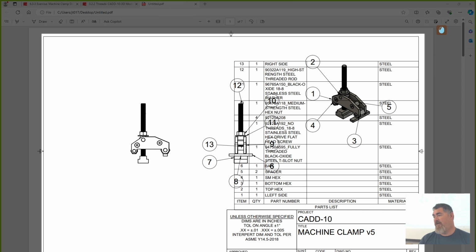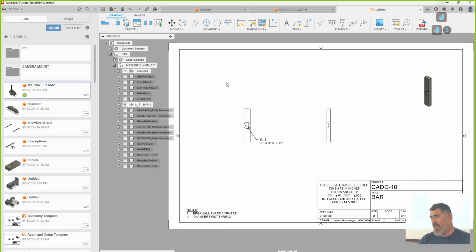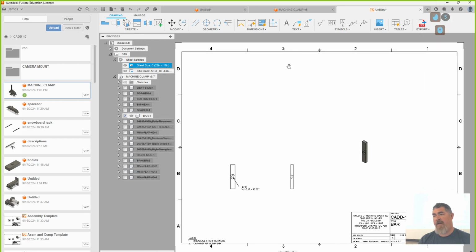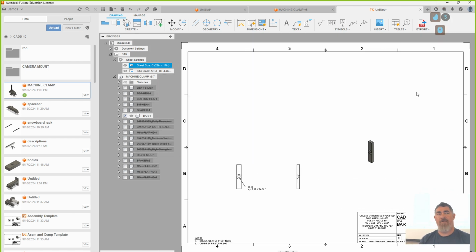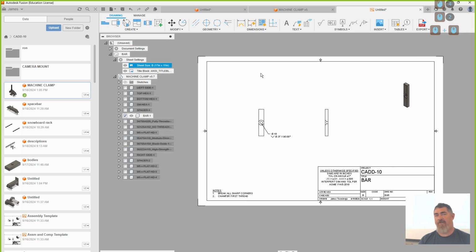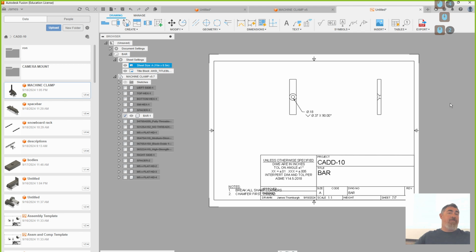What are those? Those are for the zone markings. If you get bigger sheets of paper, so if I told it to be a C instead of a B, now those break up the zones. On a B size they are smaller, so a B just gives you the arrows: upper left, upper right, lower left. On an A size, I think it's the same, because four quadrants is enough, but on bigger sheets you want to be able to break up into smaller pieces.